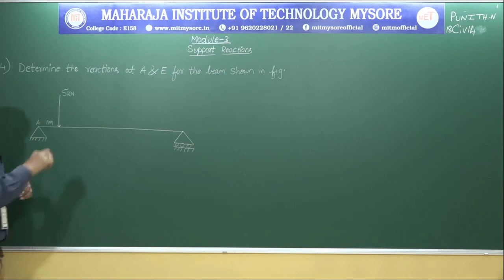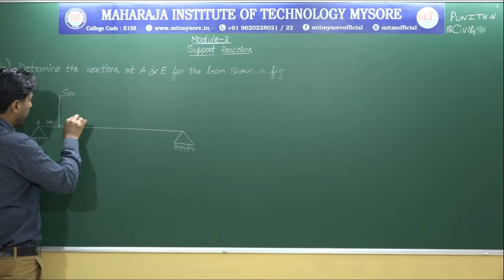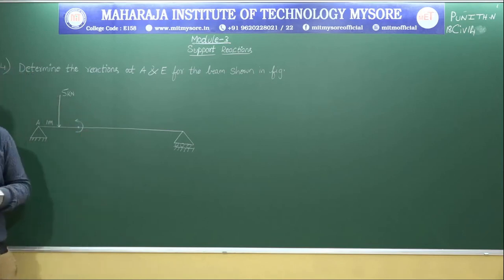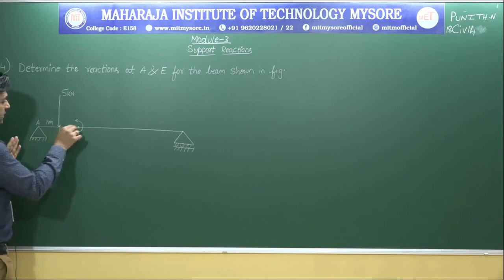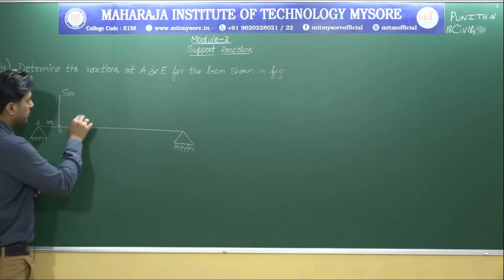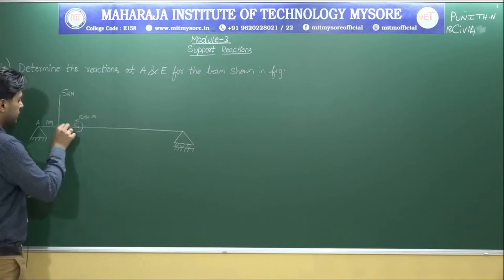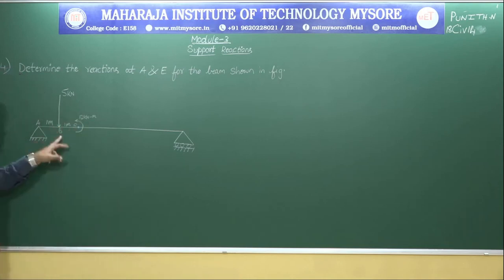So next, at 1 more meter they have given a pure moment in anti-clockwise direction. So that they have considered, this is B, this point is C they have given, and the value is 10 kilonewton meter. This is also 1 meter. So from B to C the span is 1 meter.